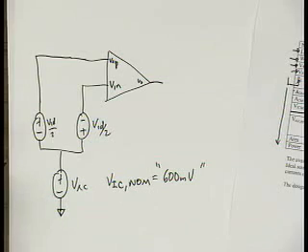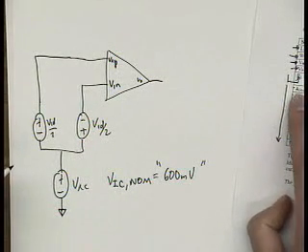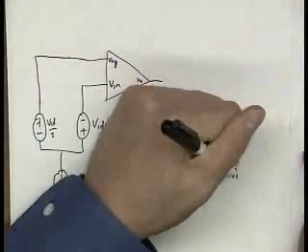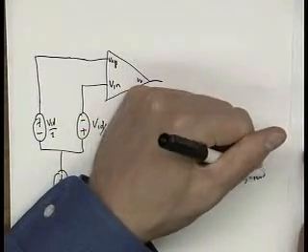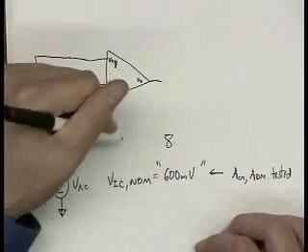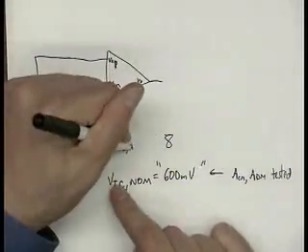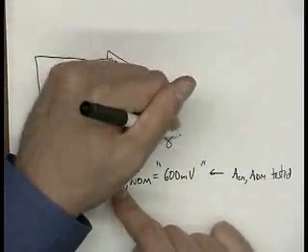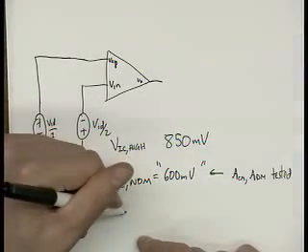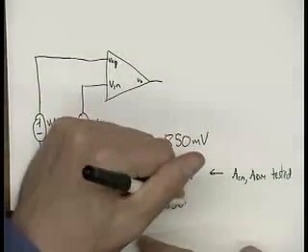So that means what we're going to do is we're going to test your circuit. We're going to test these specs, ADM and ACM, with a DC bias. And notice that I've started drawing it with all caps. VIC high is equal to 850 millivolts, and VIC low is equal to 350 millivolts.